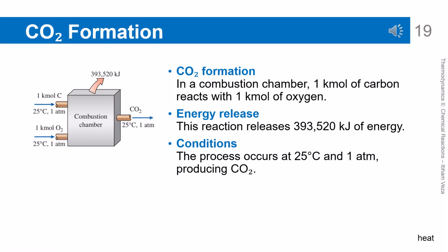CO2 formation, energy release from carbon combustion. This example shows the combustion of 1 kilomole of carbon with 1 kilomole of oxygen. The reaction produces 1 kilomole of CO2 and releases 393,520 kilojoules of energy. The standard conditions used are 25 degrees Celsius and 1 atm. This energy value indicates how much chemical energy is stored in carbon. It becomes an important reference in reaction energy calculations.